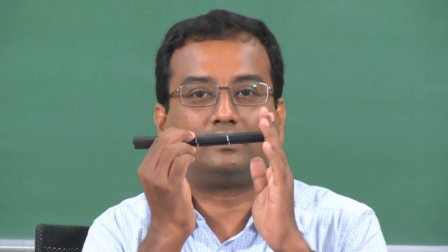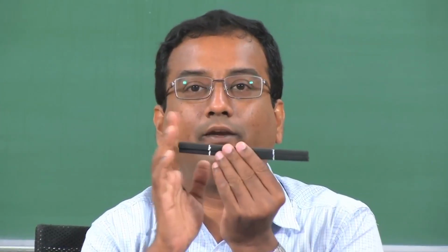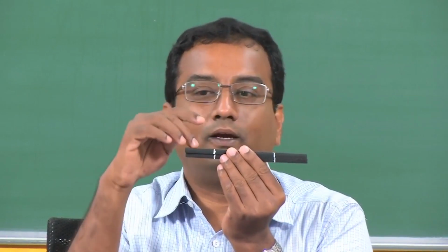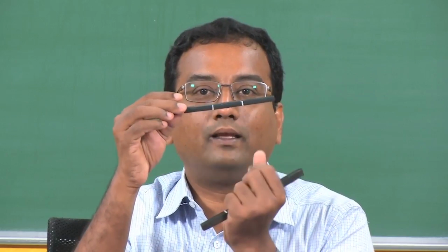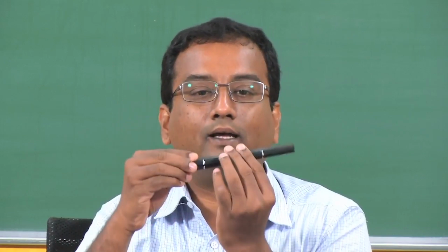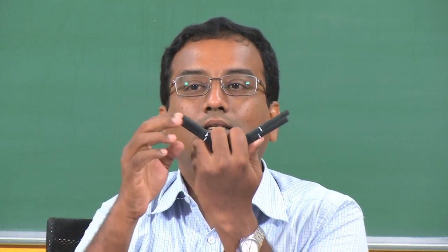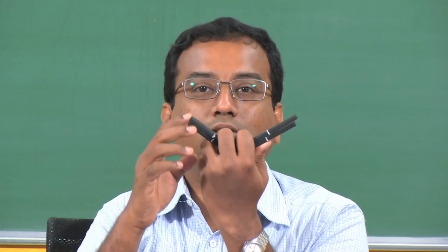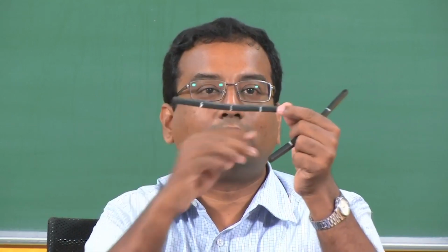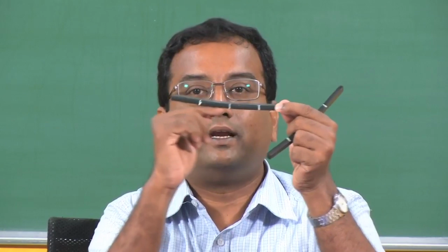Okay. As we saw here, if I have a non uniform bending moment, the axial stress that develops at this face and at this face will be different, because the bending moment is varying from section to section. If I cut one half of the beam, this half was in pure compression when I bend it, and hence the net total compressive force acting at this section should be balanced, because the bending moment is varying here. For that, it has to develop a shear stress at this interface.